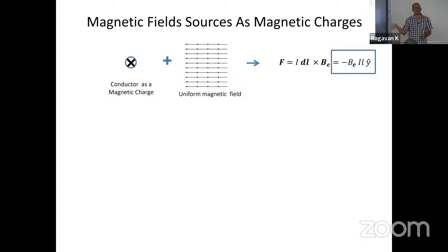if you are using such a method of estimating forces, that is method 2, you solve for the field distribution of only one source, considering all other things in the surroundings, whereas the other source you represent as a magnetic charge, right? So how do you represent it? That's a different thing. But the essence of this method is you only consider one field source. The other is simply a charge.